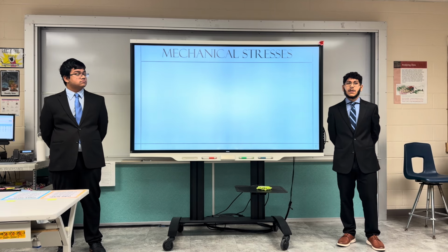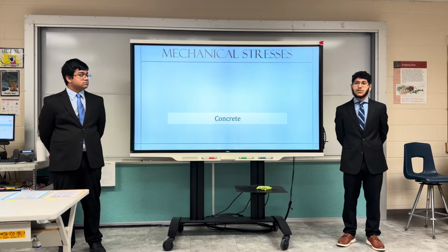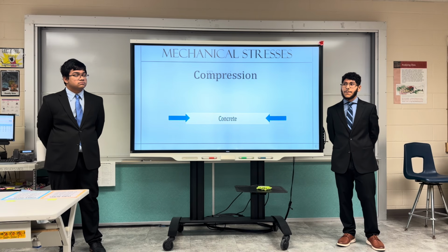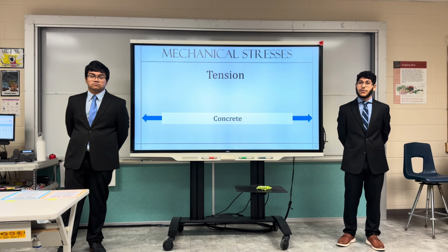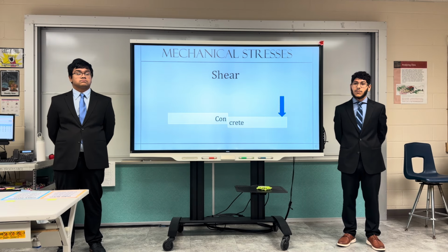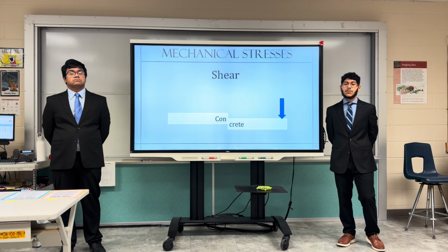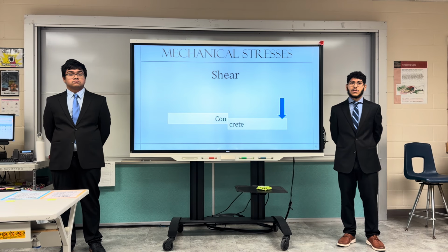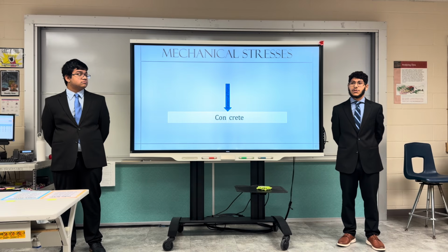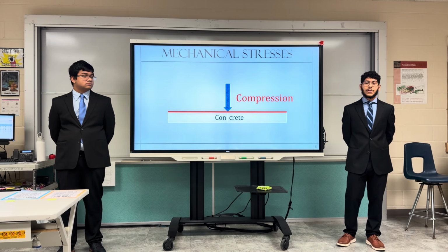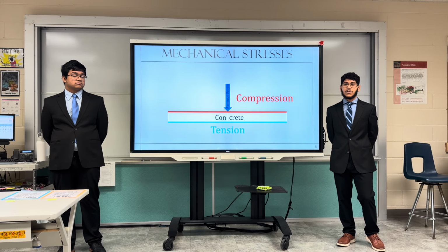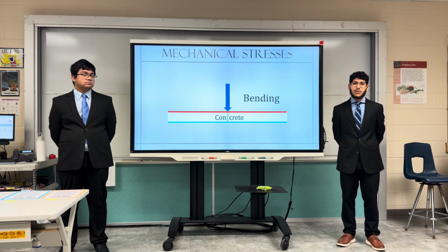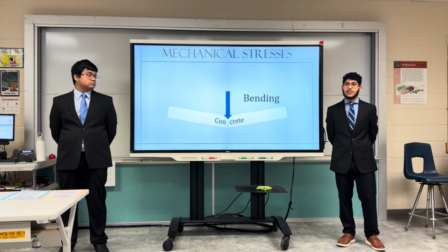In the test, there are four main types of mechanical stresses the concrete will experience. The first being compression, when you squeeze a material. Next being tension, when you pull a material apart. Third being shear, when you apply a perpendicular force to the concrete beam, causing external microscopic layers to slide and pull apart. And so in the test, when the external force is applied, the concrete will experience all three: compression in its top half, tension in its bottom half, and shear throughout, combining to make the ultimate fourth stress known as bending. And so this is what ultimately causes the beam to fail.